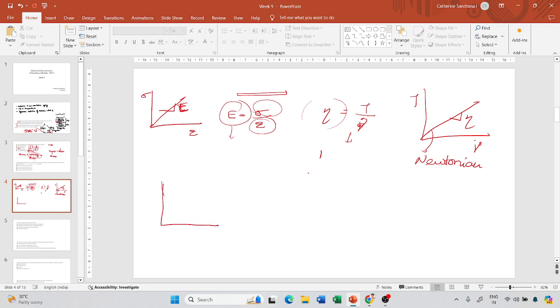Okay, so the equation of viscosity is still the same, but it will become a function of shear rate. Okay, so the equation will still be the same, but at every point of shear rate, I have to measure the shear stress and find the ratio. That is why I am calling it apparent viscosity, because it is going to keep changing with shear rate.